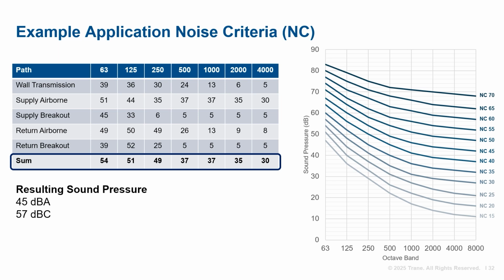And the octave band sound pressure can be plotted on the NC chart, with the result coming out to be NC39. We can also look at how well the sound pressure correlates to the NC curve sweep. This one is okay, but we could revise and do better. Software can quickly calculate these single number descriptors for us. Next, Derrick is going to discuss how equipment sound data is obtained.